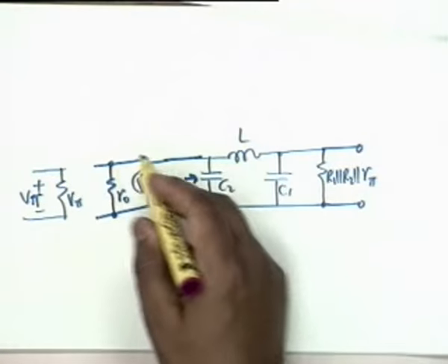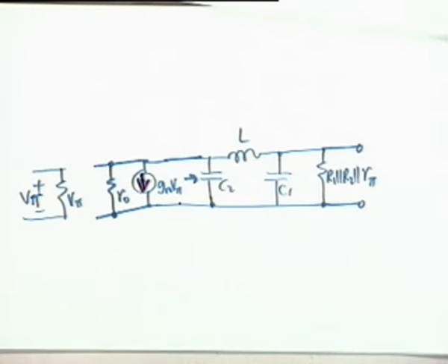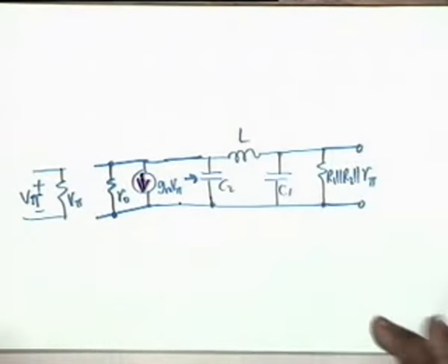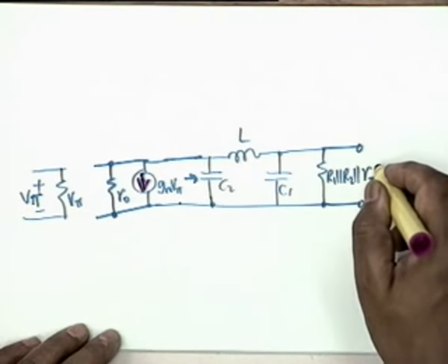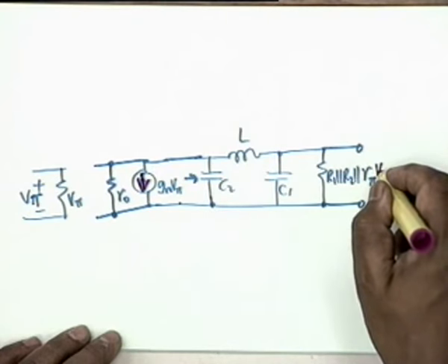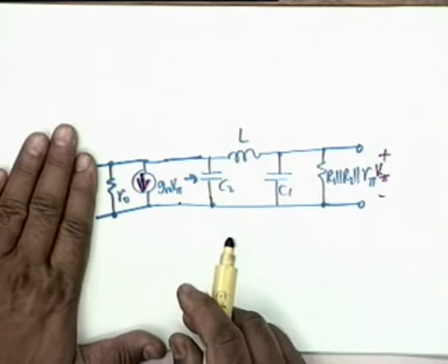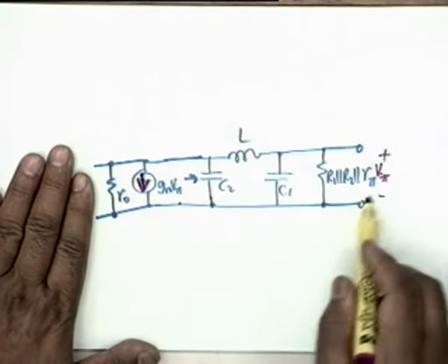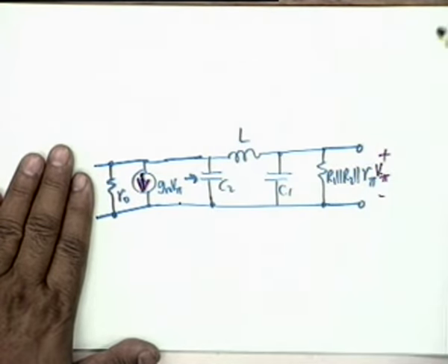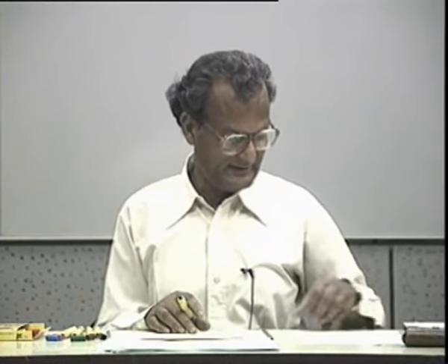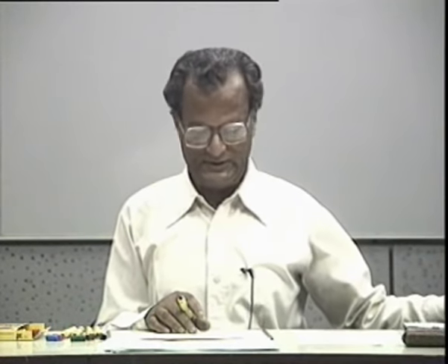This is the equivalent circuit of the transistor. Okay. So what I am mentioning is that if it is a BJT, then you shall have to be careful. You have to analyze this circuit. Now, what is the condition for oscillation now? That this voltage should also be equal to V pi. So you forget about this part. You start from here, find out this voltage, and equate that to V pi. That would give you the condition for oscillation. And this is the general philosophy of analysis of such circuits.